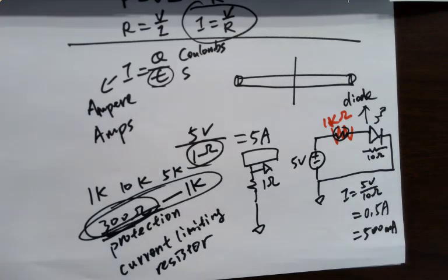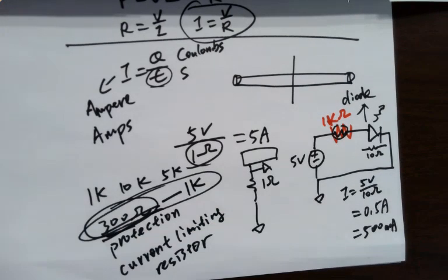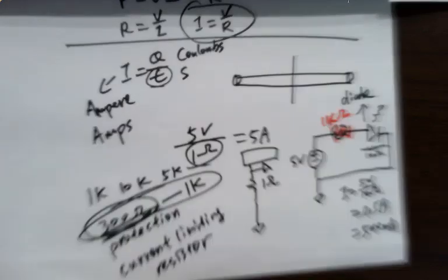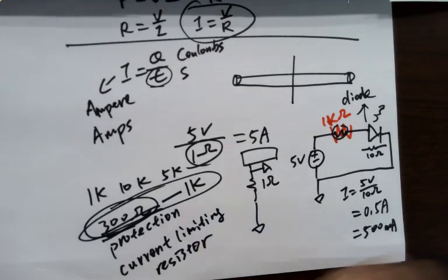Anyway, nothing below 300 ohms for digital stuff. Just grab a 300 ohms, 500 ohms, 800 ohms, 1K. It's okay. All of them are fine. You can always adjust it if it's too dim or too bright. Usually they will be fine.